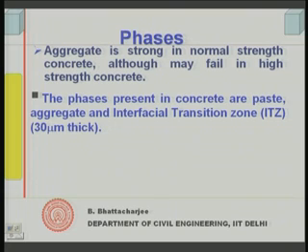The paste is obviously the other phase. This aggregate not failing also means that cracks do not pass through the sand, they only pass through the sand boundaries at best, and the sand coarse aggregate bond, because the mortar aggregate interface is where the failure takes place. So, the sands will also get separated from the coarse aggregates. So, it is all through the boundary. So, aggregate is one phase, paste is a second phase, and the third phase one defines in concrete is quite often defined as